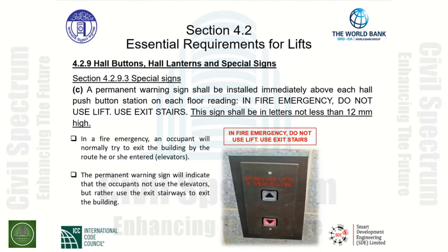exit the building. The graphic indicated in the slide shows the signage directly above the push-button station, indicating in very bold letters, not less than 12 millimeters in height, stating, "In fire emergency, do not use lift, use exit stairs." This is the location that it needs to be installed, so the occupants can clearly see the instructions in case of an emergency.